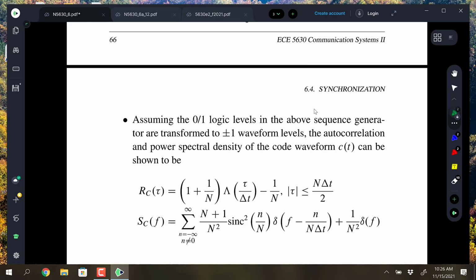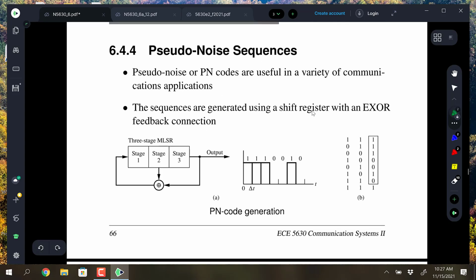In my real-time DSP class that I teach in the spring, Gold codes have been used in that class too, but just PN codes, you implement it in C, and you can do it very efficiently with a single, say a 16-bit integer, and then you can do all the bit manipulations in right shift and left shift and hold your shift register just in one 16-bit integer, and then you can handle up to 16-bit long patterns, and then you just code it all like that.